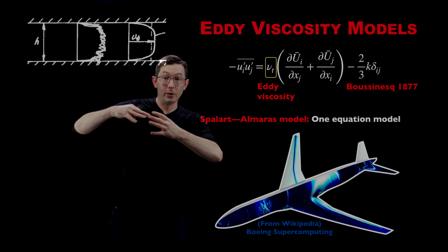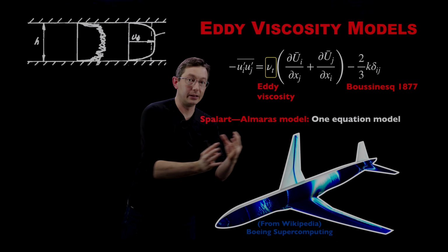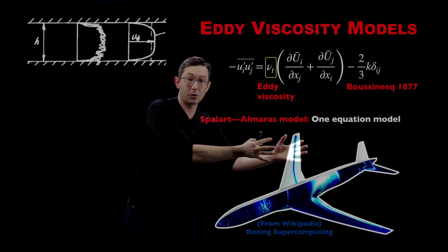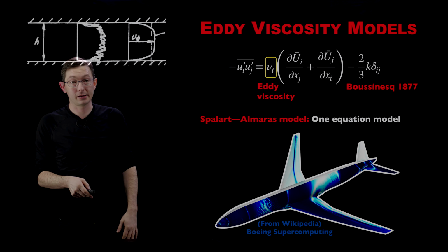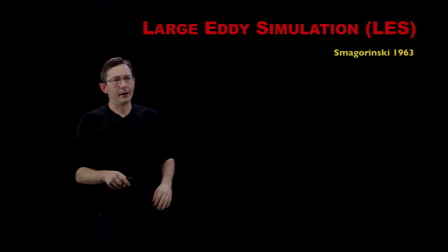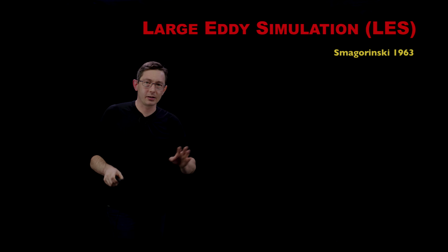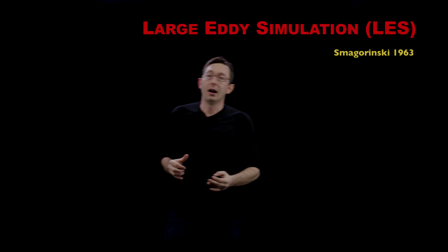You can change or tweak the geometry of your wing and fairly rapidly figure out what these average quantities are going to be, and then re-optimize and redesign based on these predictions. So this one's really, really useful, a cornerstone of aerospace engineering. Okay, good. So that was turbulence closure modeling using the Reynolds averaged Navier Stokes equations.